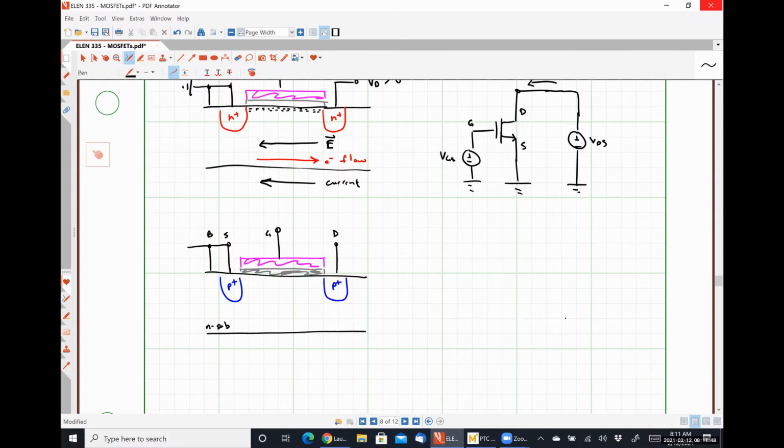There's really two ways to do it. One is the way the textbook describes it, and it's the way that I don't really care for. Negative voltage on the gate will absolutely do it. Here's why I don't like that, okay? Typically speaking, you would see on a PMOS transistor that the source is at the highest potential in the circuit, unless there's a resistor or something like that in the way. So I'm going to tie both of those guys to VDD.